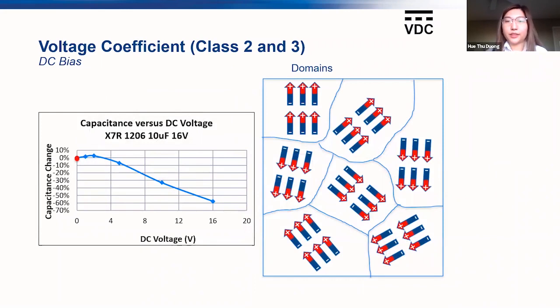When barium titanate goes below the Curie point, or 130 degrees C, the dipoles will align to create domain regions, as you can see here. And these regions will be randomly scattered in all different directions within the dielectric material. The overall net effect is a cancellation of all the dipoles within the material. The process by which barium titanate creates dipoles, and those dipoles being randomly scattered throughout the dielectric, is called spontaneous polarization.